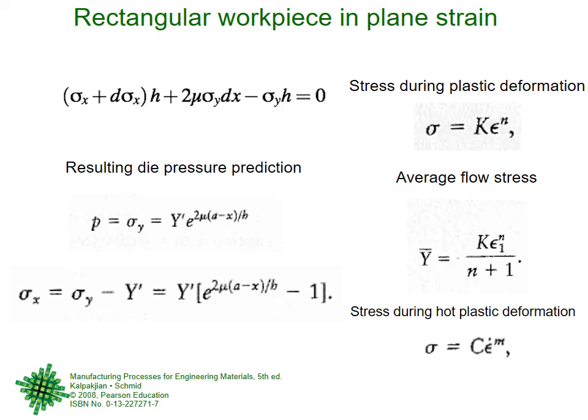So every time, these are some forces which are known, these are some forces which are unknown, and you apply the condition and then you are done. So here when you balance out the forces in the x direction, you see sigma x is the stress, multiply it by the height h, any height h, unknown height, right? Any height h. And the other dimension, if you take it as unity, remember, right? It is a face, h is the height, and there will be some depth. So in the depth, because you are not doing a 3D, in the depth take it equal to 1. So h into 1 is the area.